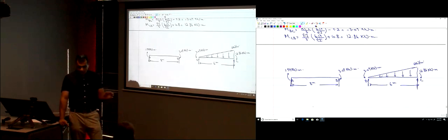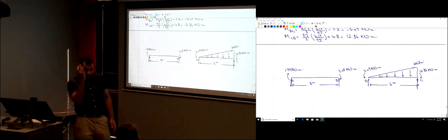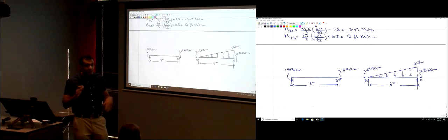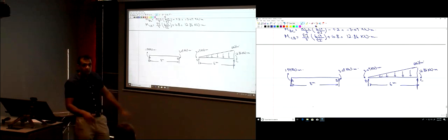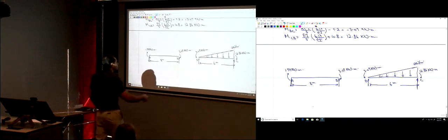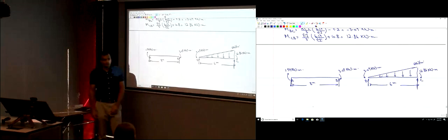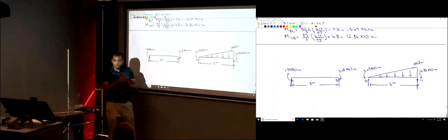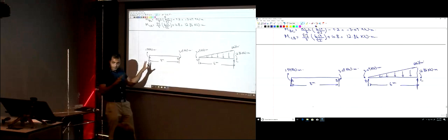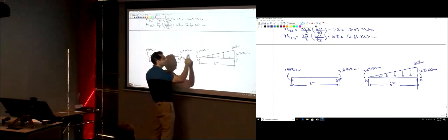We're calculating the moment at the critical points. How do we calculate the moment at the critical points? Break the beam into two halves, right? At point B, we already broke it, to two parts. And then find the moment here at point B, either from the left or from the right. How much is MB? 3.09. It's not 0. I'm not adding those together. I break the beam. It's already broken now, and then I find it either from studying the equilibrium of the left part or the right part. So MB is 3.09.